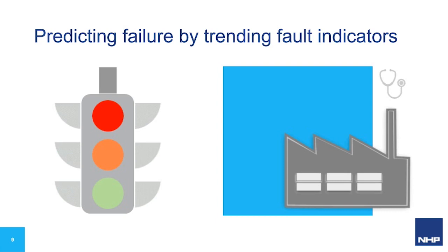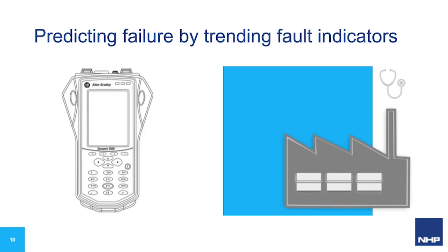For example, a misaligned shaft may cause a coupling to lock up, or an unbalanced or misaligned shaft will add stress to bearings, reducing bearing life significantly. Compounded faults will cause longer and more expensive repairs, or repairs that do not actually solve the root cause of the problem. So vibration rules are well known and proven, and that's why we use vibration.